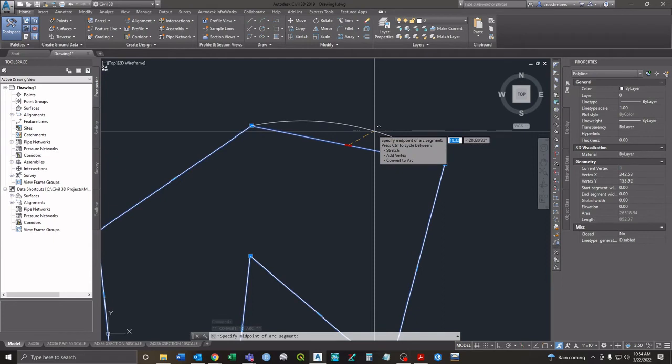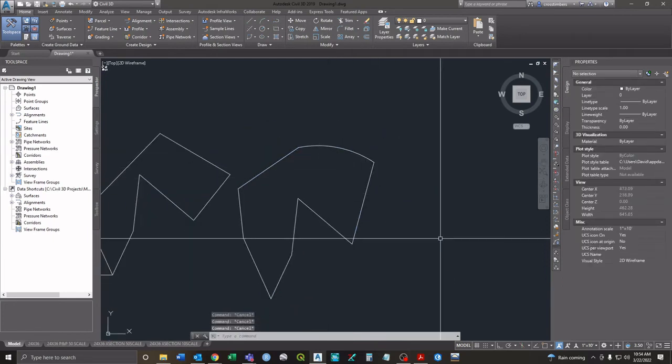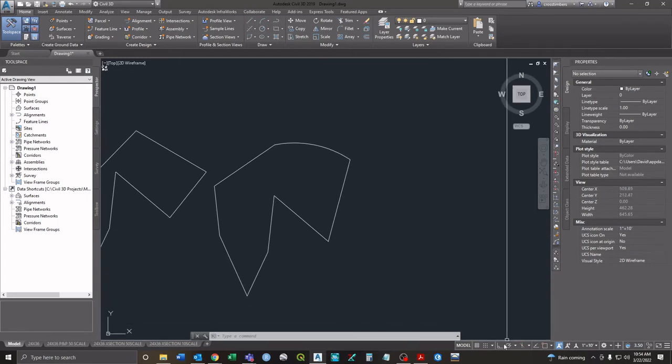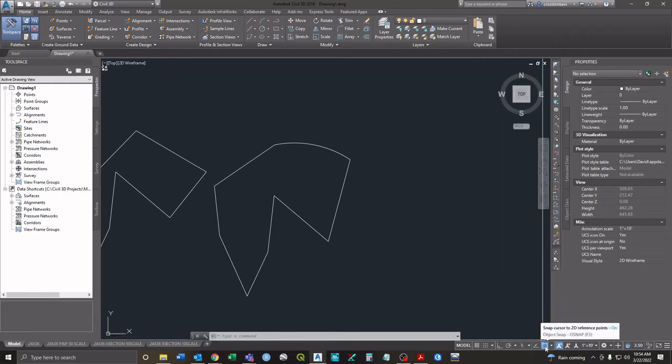So what did you do to click on to just keep the snap on? Okay, so alright, that's something we'll get to in just a second. So we can do that. Okay. Yeah. Okay, so we did the ortho, right? We clicked that button. Okay, so you can either hit F3 or click this thing down here. Alright, so you can basically turn it where the snapping is on all the time, right? And then within that, you can set which snaps are on all the time.